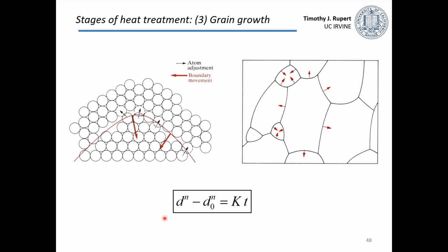Now, at some point, we'll have these new recrystallized grains. If we keep giving the sample time and temperature, those grain boundaries, which again are defects, can keep moving. Those grains can keep growing to try to get rid of those defects. So we can think about that new recrystallized grain to keep growing and maybe get rid of a smaller grain here.